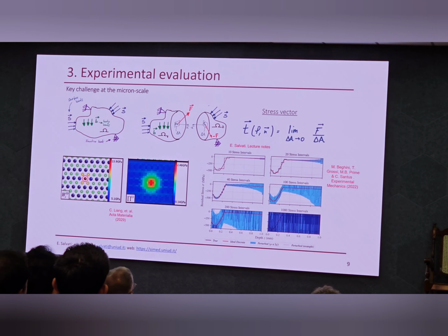Destructive techniques essentially have, if you exploit the focused ion beam, a technique that cuts material at micron scale. You might perform some slits, then with digital image correlation you keep acquiring images of the surface, and then you can track the deformation of the material. Okay. Some people use, well, all of them use finite elements then to go back and reconstruct the residual stress that has been relieved.